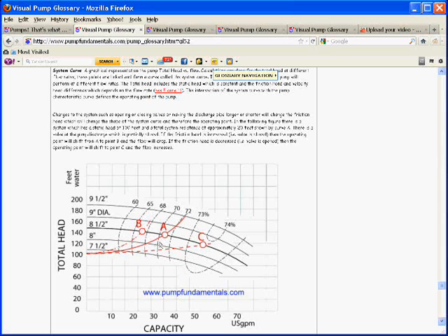And then you would see that by increasing the speed, you would always be on the system curve, but if you increase the speed, let's say this was the 800 RPM, and this was the 900 RPM. If you increase to the 900 RPM, you automatically ramp up on your system curve and meet the 900 RPM curve, and this is a way that you could get higher flow with the same system. So I don't know, I hope this helps. This talk about the system curve.